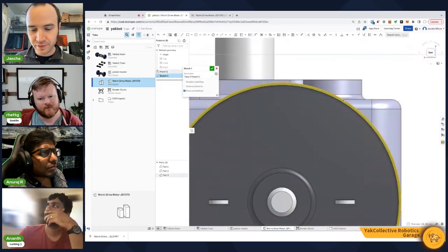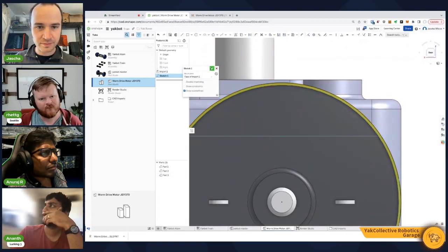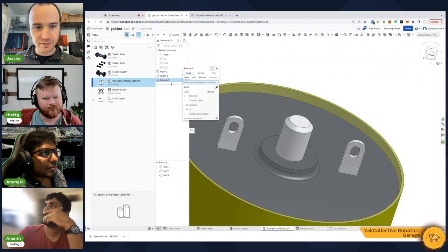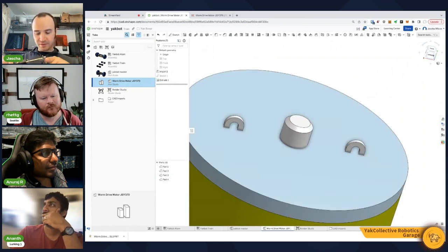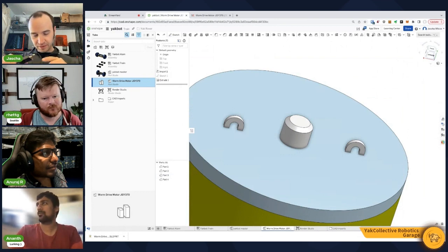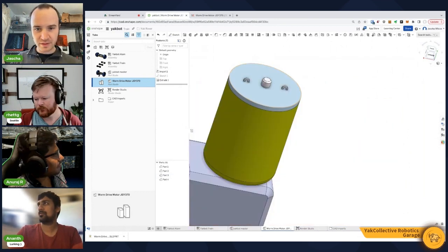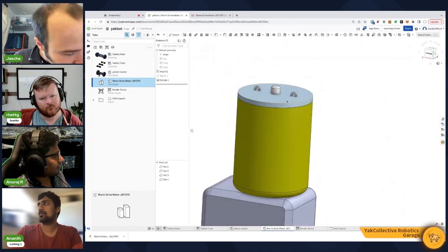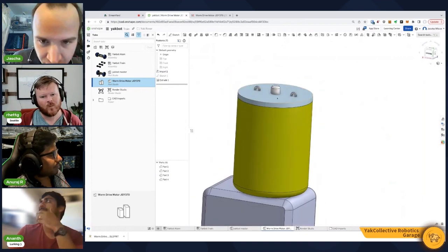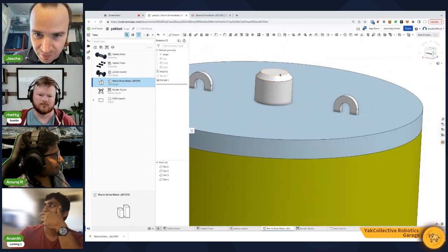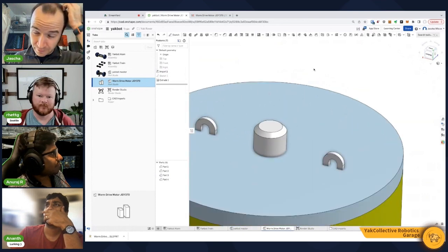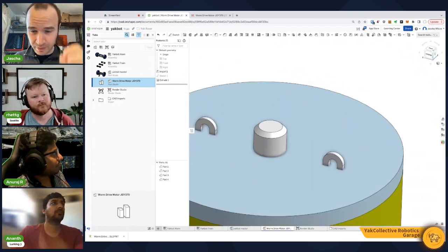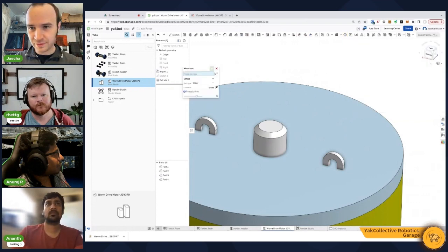So we'll do convert. Then we'll extrude that 1.6 millimeters. Okay. Because the PCB thickness is about 1.6. Yeah, 1.7. Okay. And then we will also move this face. So it was 80.8, and then it needs to be 85 and a half. So 85 and a half. That's like 4.8 millimeters.